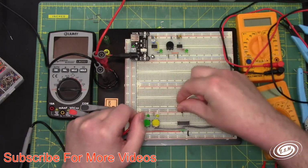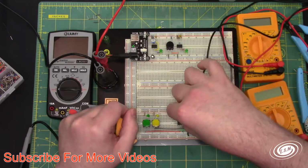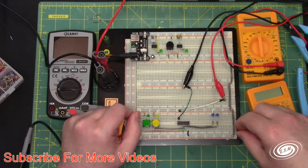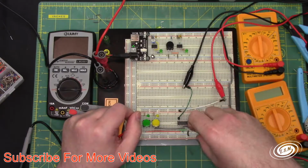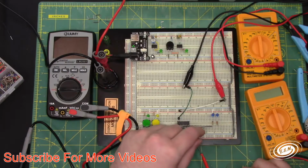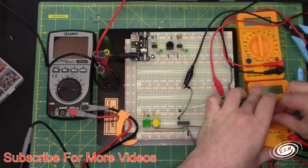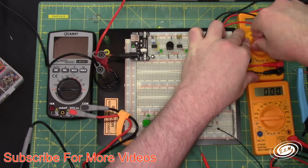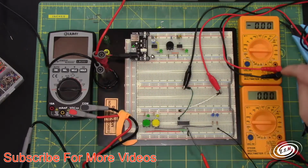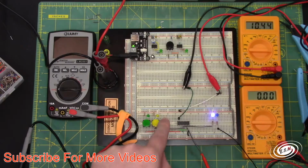Let's check the current draw of the chip, because I want to see if it's different from the last chip, which was about 0.05 milliamps, and then we will get this out of here, and we will check it to subtract the amperage. So I'll go to 20 milliamps, so you can see the meter. This is the chip and this is the LED. We will turn on the circuit and press the button.